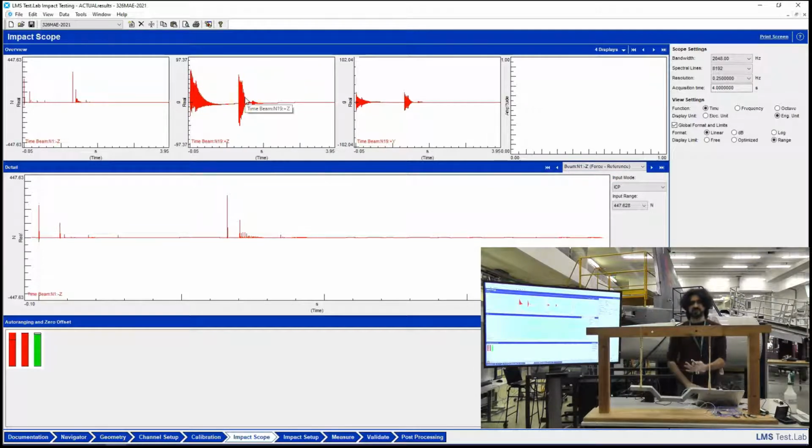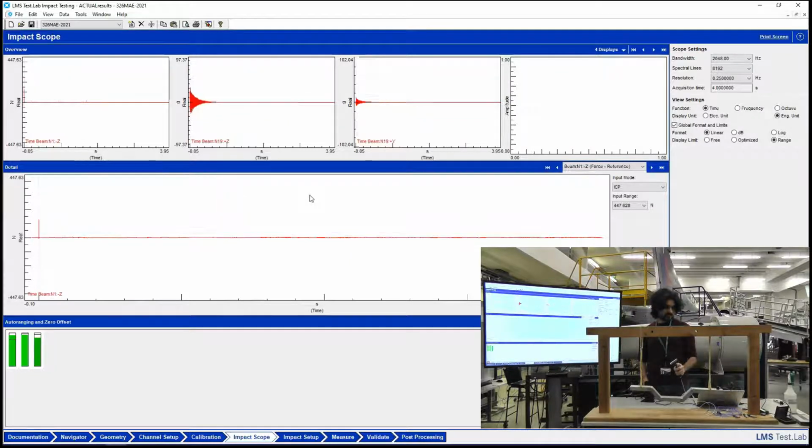And of course, if you do the fast Fourier transform of this, you also get very large errors everywhere in the spectrum. So you must be very careful to capture a single decaying set of sine waves and a single spike in the hammer. Ideally, the technique would be to have this ready and to grab the hammer from its center of gravity, say around here, so you can easily remove it as soon as you strike. Yeah, something like this.